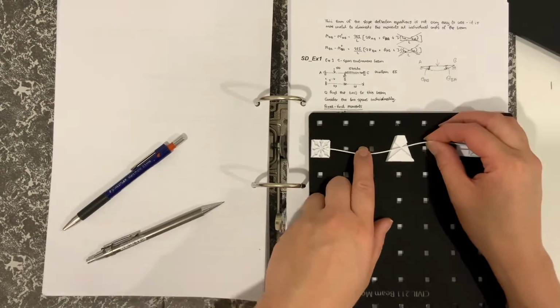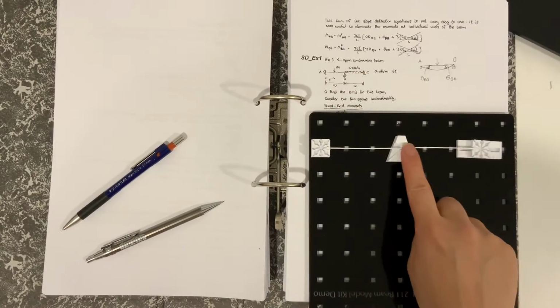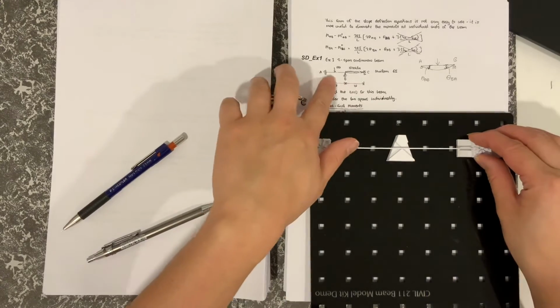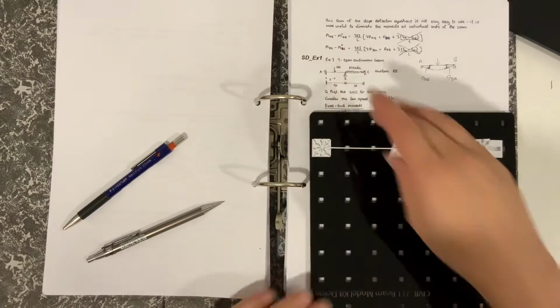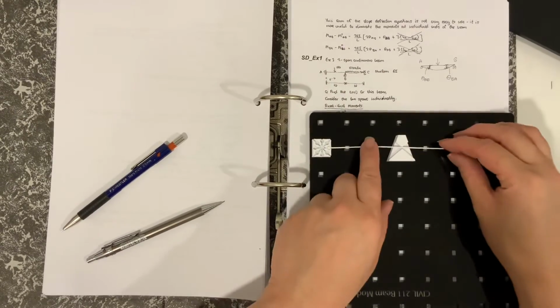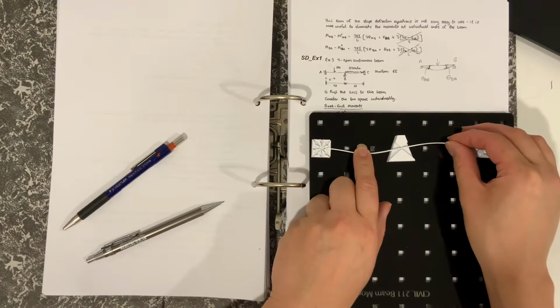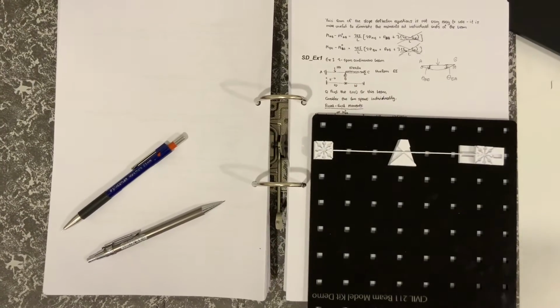Okay. And that's because this load is more evenly spread out over this part of the beam. So in other words, having the 100 kilonewtons as a central point load would lead to more rotation, a stronger one, causing a rotation in the anti-clockwise direction at that point at B.